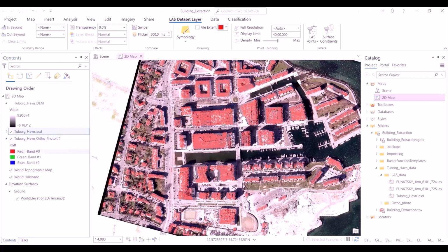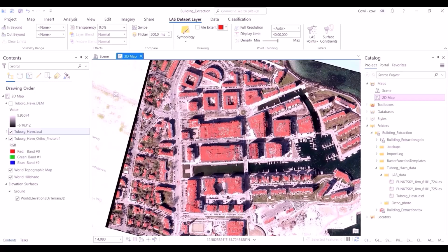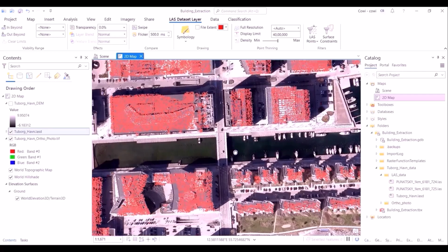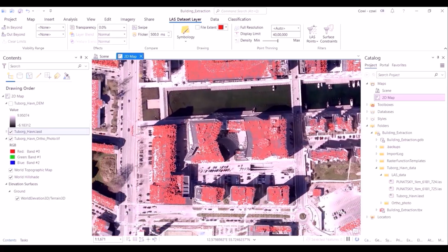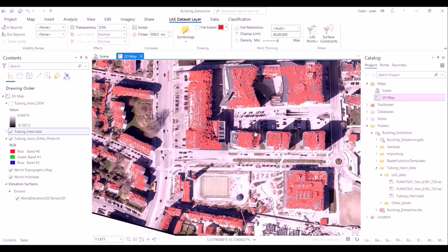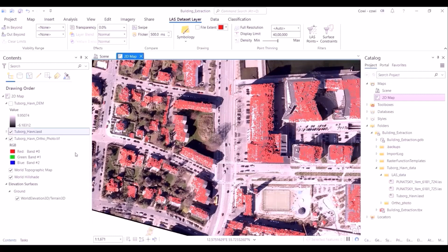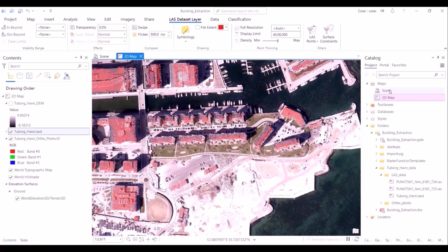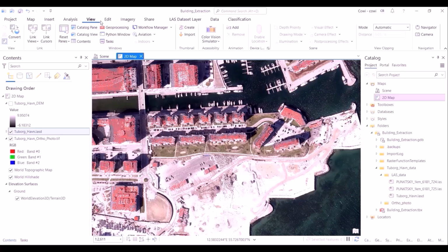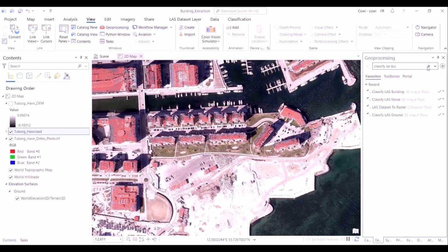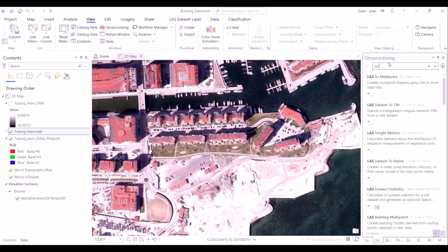The red pixels on the screen are the building footprints which have been transferred. When we overlay it on top of the ortho-rectified imagery, you can see more or less the buildings have been clearly identified, although there is a difference in perspective because the ortho-rectified image was captured from a particular angle, whereas the airborne LiDAR imagery was captured from another angle altogether.